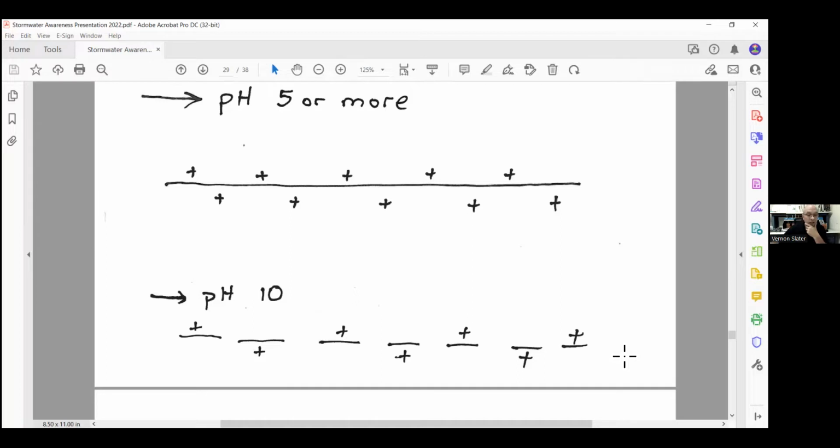And does chitosan work with truck wheel washes? In many cases, yes. However, there are pH limits. So a truck wheel wash from a concrete plant, where elevated pH would be expected, chitosan would not be the best choice. When used on muddy sites where track-out pH is 5 to 8.5, expect very good reaction from chitosan. Recommended uses might be with a system like the Moby Dick truck wheel wash, with automatic sludge removal, or by battering out sludge after some settling time.